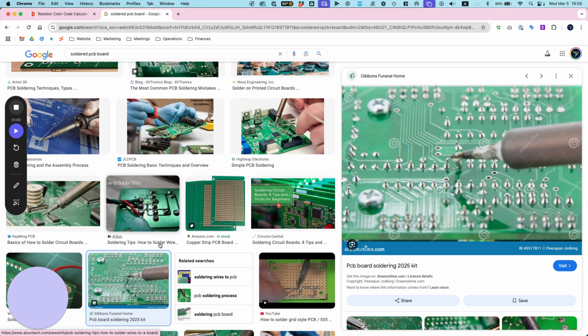You see, this is stuck on the solder sucker. That's the extra solder that's come out. So I got some out. Okay, again, these are physically bent over. We don't really ideally want to bend these wires over. They should all come out straight, and then you clip them. Yeah. So there you go. I can now free this part. I think I have too much solder still on this end. So let's use the solder sucker to try to get some of that out.